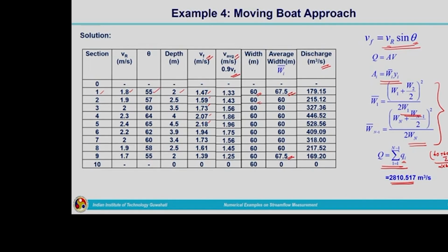So, in the problems related to non-prismatic channels, area computation is the difficult task. It is not actually difficult, you need to take more care to find out the average width corresponding to the first section and last section. You do not have to memorize that particular formula for computing the average width. How it is coming, by making use of the simple similar triangle principle you can calculate.